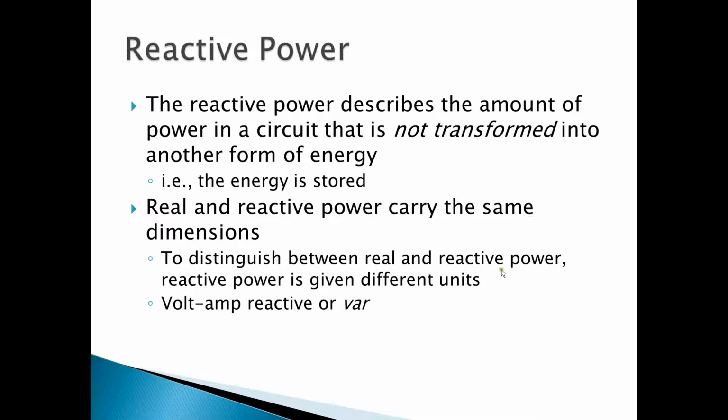But to distinguish between the rate at which energy is dissipated and the rate at which energy is stored, that is the real power and the reactive power within a system, we give them different units. So real power is expressed in watts, and reactive power, or the rate at which energy is stored within elements of the system, is given units of the volt-amp reactive, or VAR.